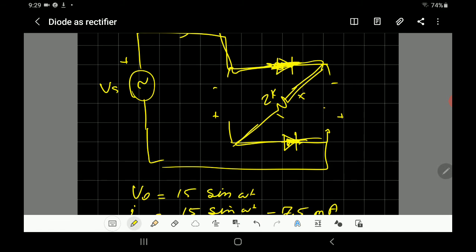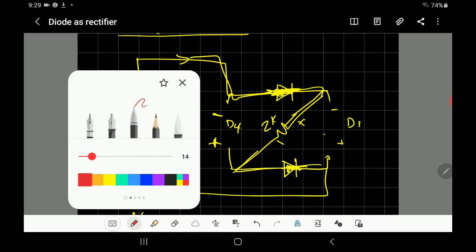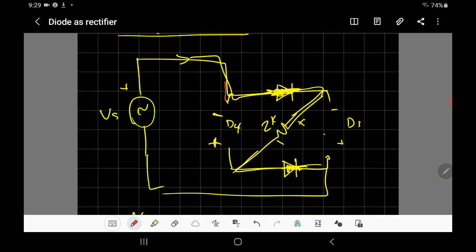But let's just find the voltage across any diode that is disconnected, like D3 and D4, any one of them, because they are equal. Let's say, what is the voltage across D4? That's why I left the polarity on D4. You can find it by taking any closed circuit. I will mark it in orange, because Kirchhoff's law needs a closed circuit. I'll take this circuit.